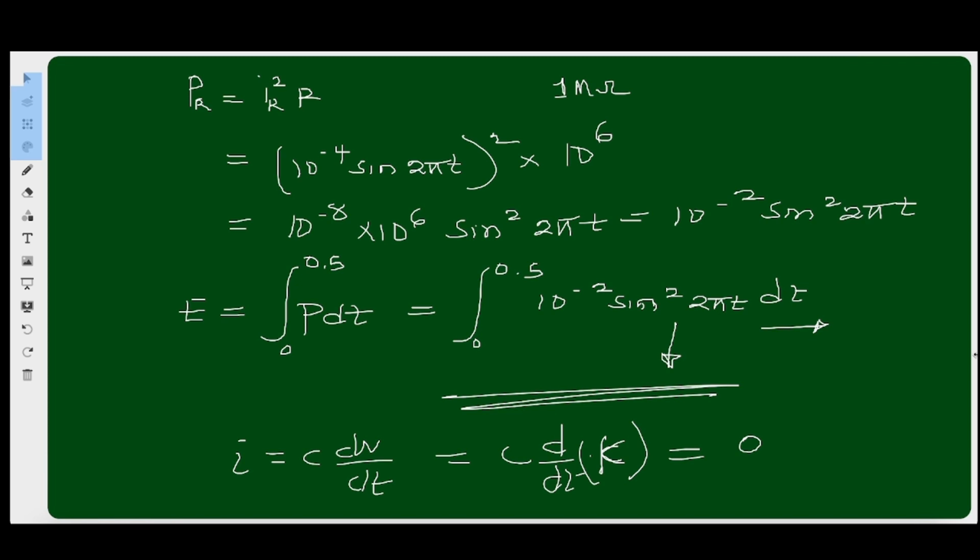And the third one is that it is impossible to change the voltage across a capacitor by a finite amount in 0 time, as this requires an infinite current through the capacitor. What does that mean? It means that a capacitor resists an abrupt change in the voltage across it in a manner analogous to the way a spring will resist an abrupt change in its displacement.